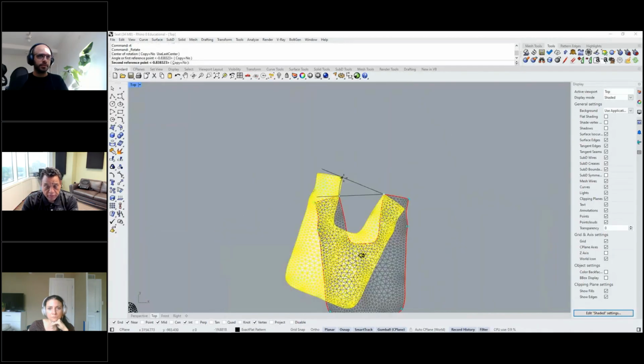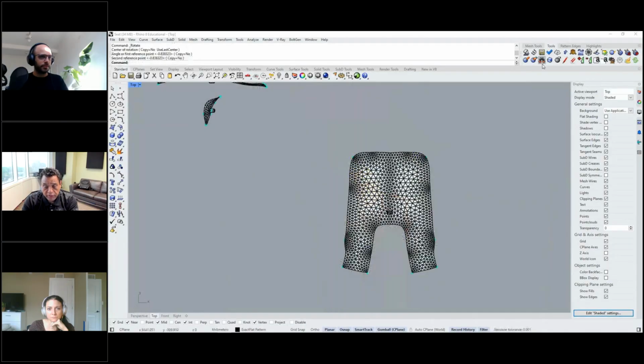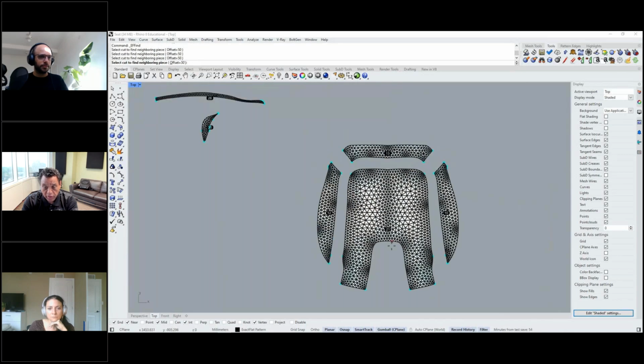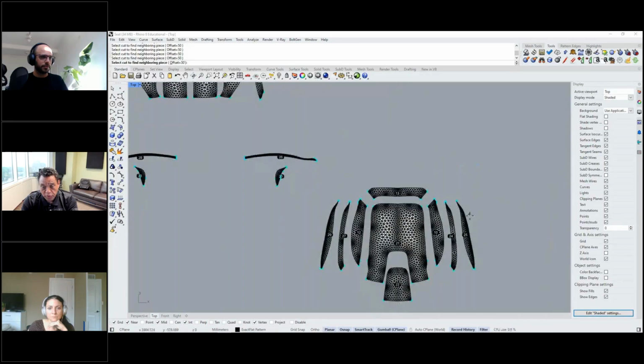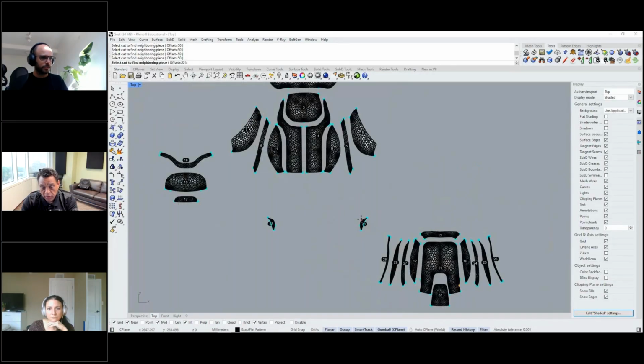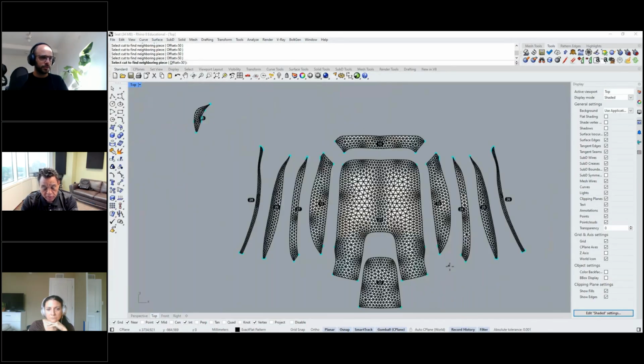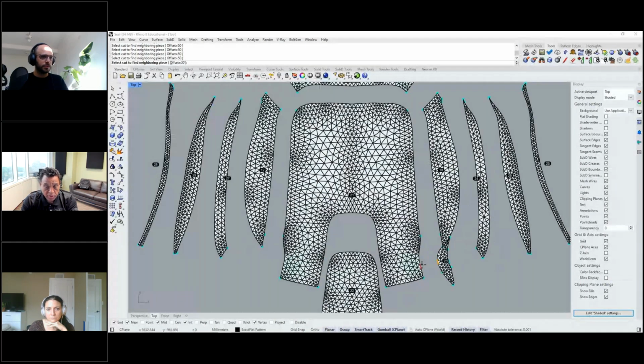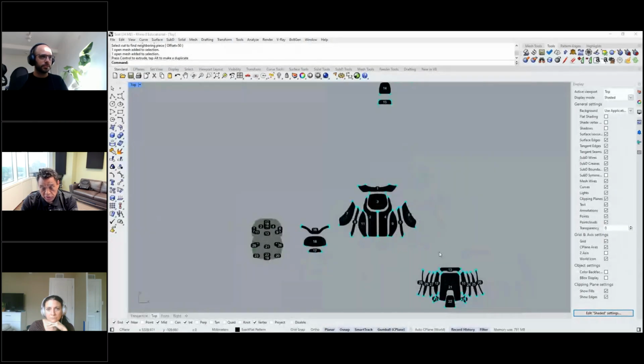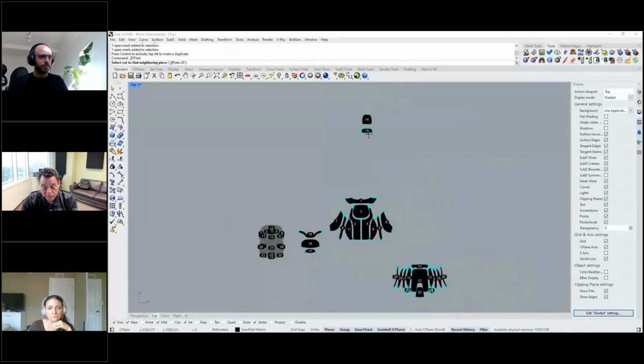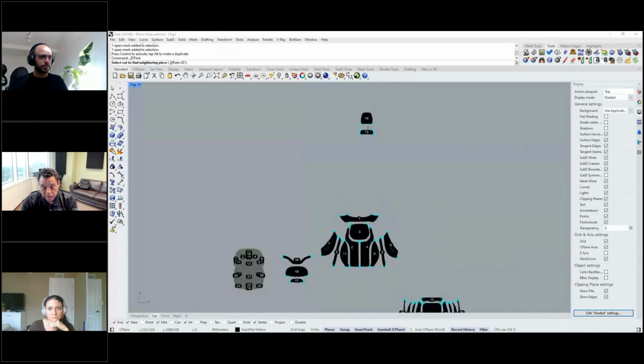The process that makes ExactFlat unique here is that all of the locations of those vertices, these are the intersecting points on the triangular polygons, have been indexed from 3D. And we maintain that indexing through to the 2D process. Even as the mesh elements are being redrawn and potentially the pattern geometries may be cut later on, all those locations are indexed. So we can automate this process of laying out the pattern pieces and easily find them so that you can